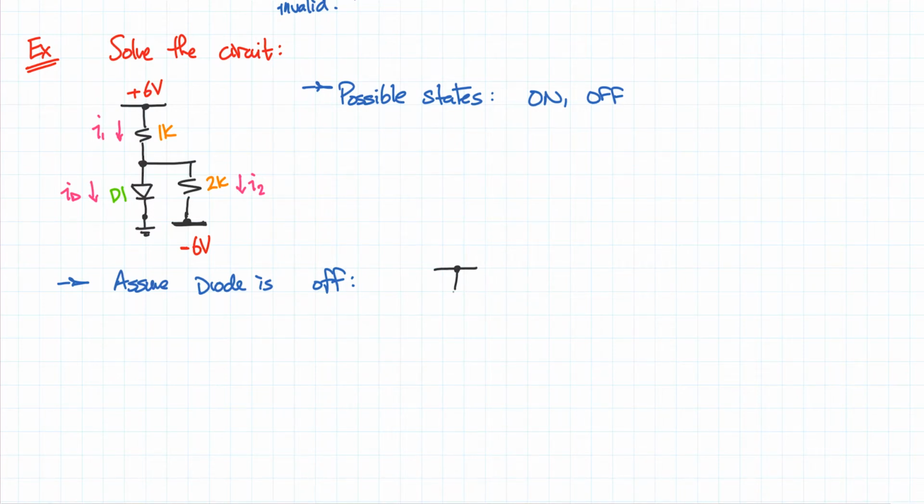because they tend to simplify themselves quite a bit when you redraw things. And that usually makes the analysis a little bit easier than if you're just looking at it trying to imagine. So this is minus 6 volts, and this is 1K, and this is 2K, and we had I1 here, we have I2 here, and in this case, clearly I1 equals I2, right?